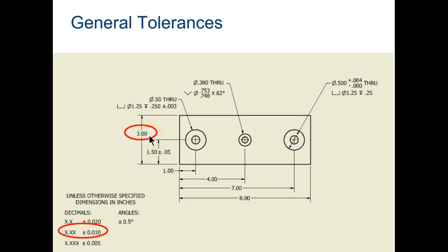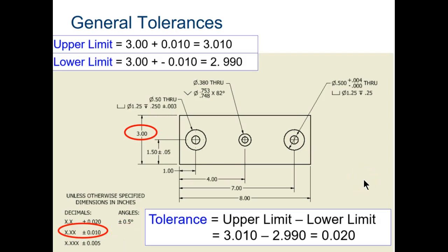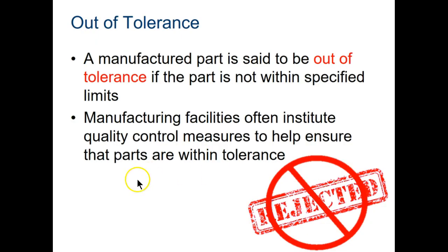So this number has 2 decimal places, so it's going to be plus or minus 0.01. In that last decimal place, it can go up or down by 1. And it shows you that. So that's how you would read that. So most of the time, you just type up this little table somewhere on your drawing as text and run with it from there.